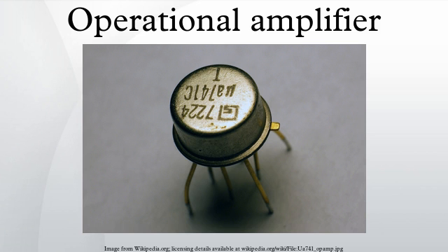These op-amps were effectively small circuit boards with packages such as edge connectors. They usually had hand-selected resistors in order to improve things such as voltage offset and drift. The P45 had a gain of 94 decibels and ran on plus or minus 15 V rails. It was intended to deal with signals in the range of plus or minus 10 V.